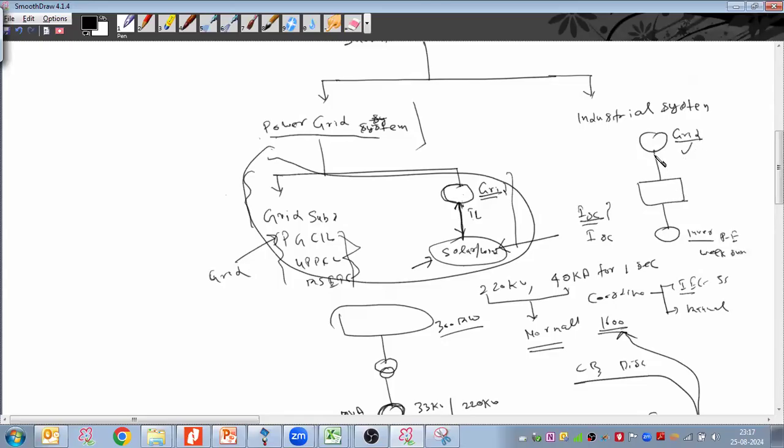You are putting a transmission line that has resistance and reactance, so you are getting some fault current here. That current I'm going to use for all the earthing and CT calibration. But for the equipment, there are limitations: equipment manufacturers do not manufacture equipment of different short circuit ratings. They manufacture single equipment based on the grid short circuit rating. So every solar and wind substation has to use that equipment only, and that is good. You are getting 15 kiloampere, you are using 40 kiloampere equipment.